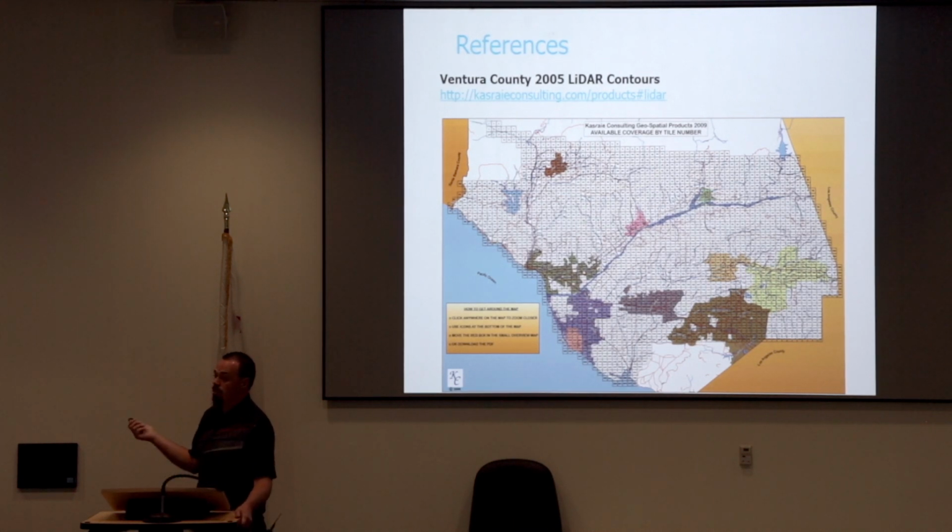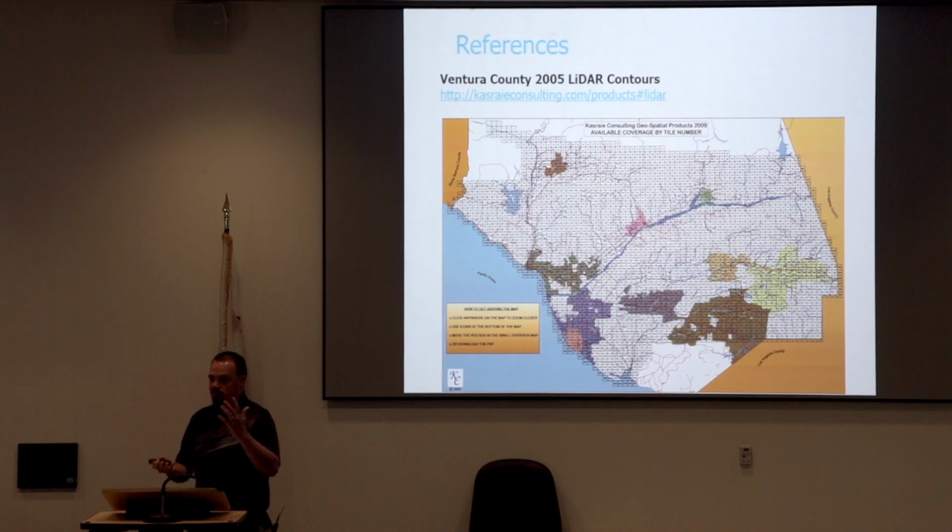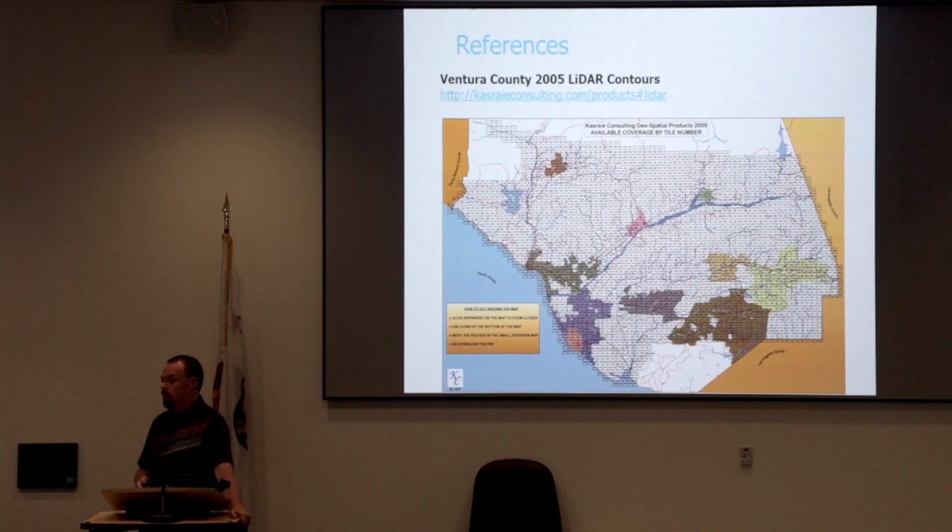It also helps with drainage delineations if you're doing your own project designs, hydrology, identifying if there's crowns in the streets, if you're having watershed to the sides, where all the drainage is. I've used this extensively for my own designs. Obviously not construction level, but for conceptual, it's 1 foot resolution. It's not exactly survey quality data, but it's something you can use for all your conceptual designs, and then as you come up with your construction plans, do your field survey to actually get construction level elevation requirements.